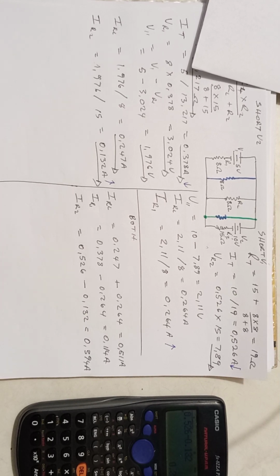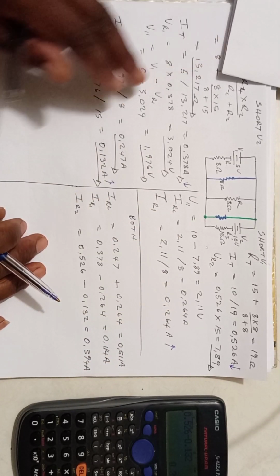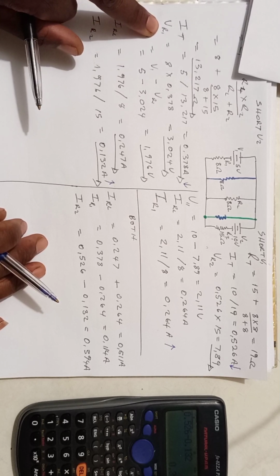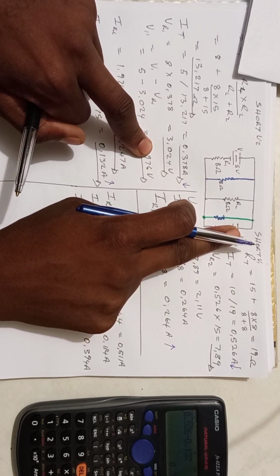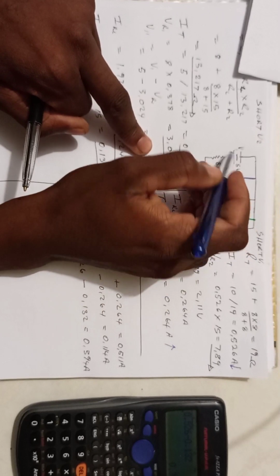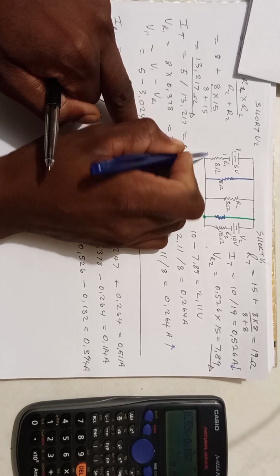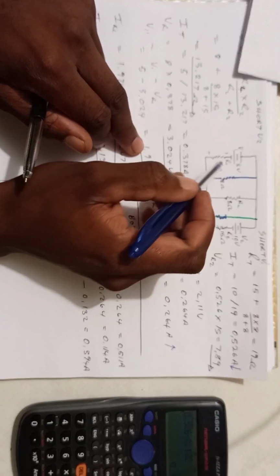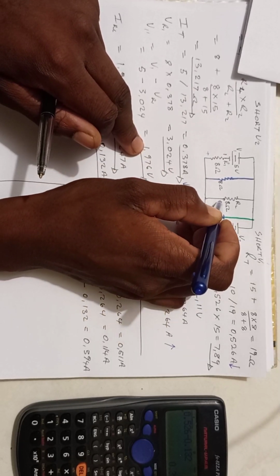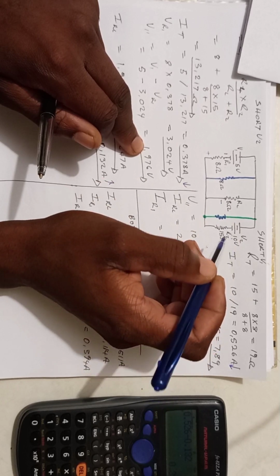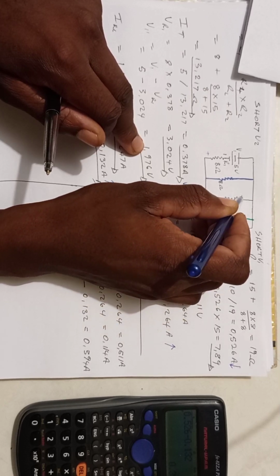The voltages, every voltage that we calculated was not for both circuits. So let's come here to the voltage across R1. When we shorted here, what was happening here? This resistor was negative there, then positive to this side. So if electrons flow this direction, this makes this one negative here and this one negative here, then positive that side, positive that side.